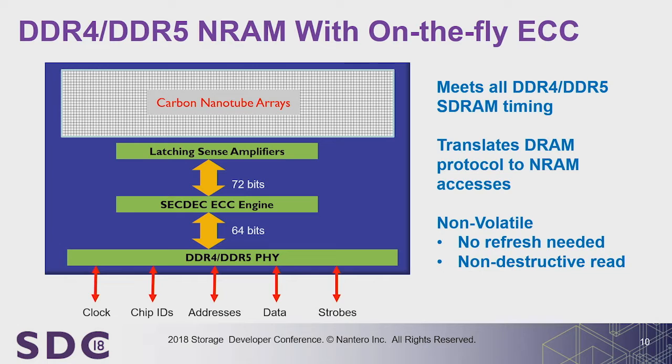Two ways that we deal with that. One is we just do post-package repair and map around bad blocks. But the other one is that we do accommodate that we might miss something in testing. So every one of our designs does a full single bit correct, double bit detect, error correction scheme on the incoming data. So we bring the data in, translate 64 bits to 72 bits, and we store all 72. When we do a read cycle, we collapse that 72 back down to 64 and ship it out on the channel. That was not in DDR4.